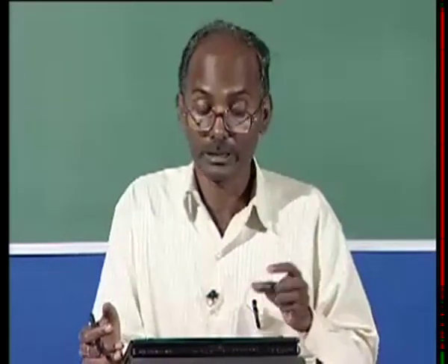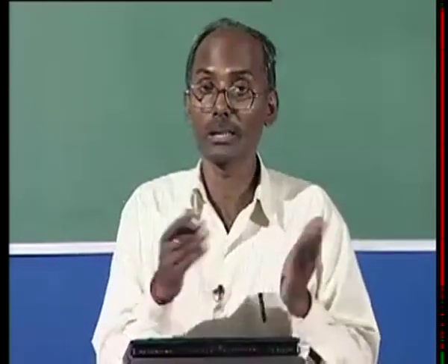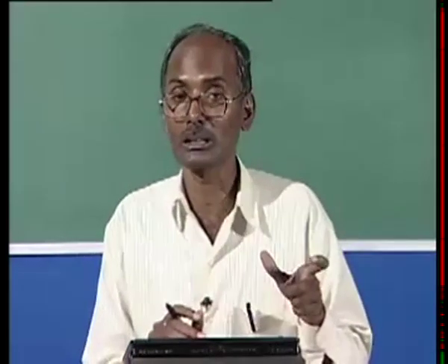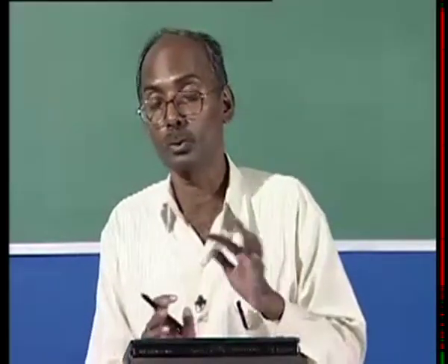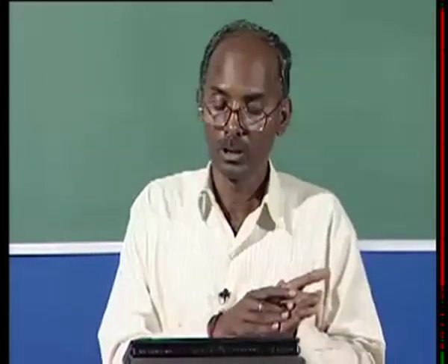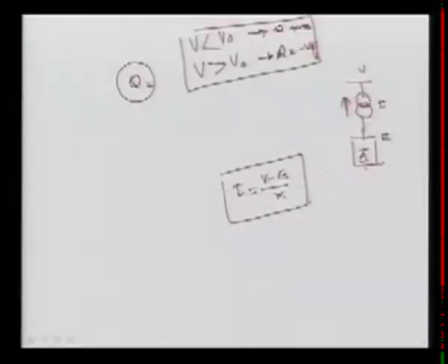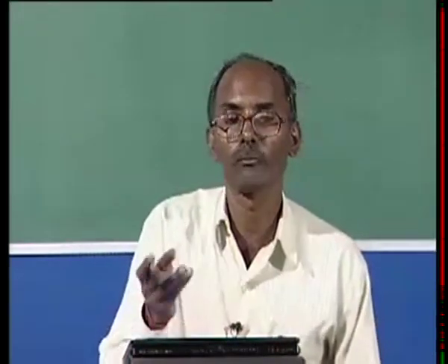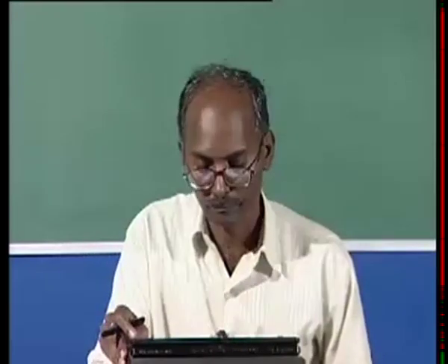As I saw, using these devices we can change the transient stability limit, and at the same time we have to model their dynamics as well if we want to see the impact together with the system dynamics. So the modeling of these devices in the dynamic is equally important, and normally they are modeled by simple single order equations, a current source, or in the case of a TCSC, a variable capacitive impedance, and then we can go further with different time fractions.